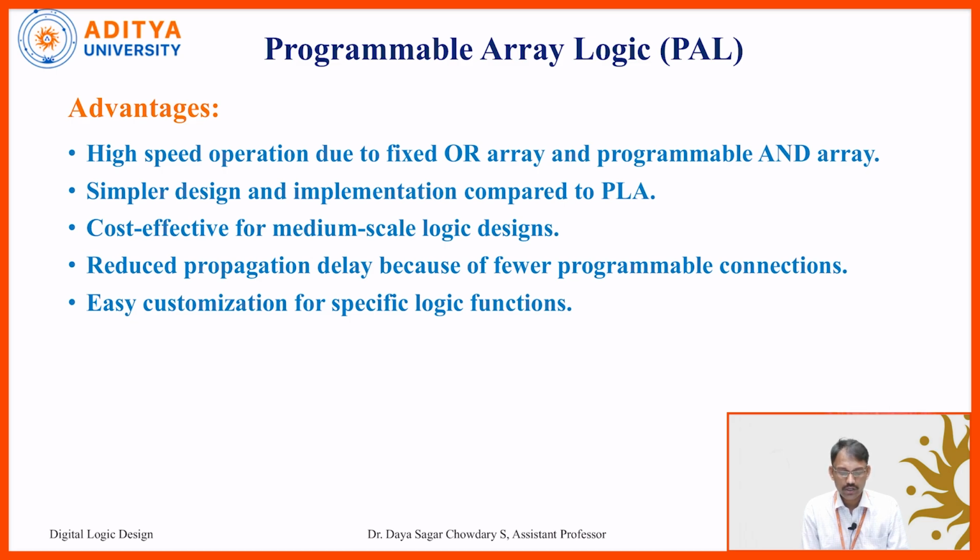And coming to the advantages of PAL: high speed operation due to fixed OR array and programmable AND array, simpler design when compared to PLA, cost effective for medium scale logic designs, and reduced propagation delay because of fewer programmable connections. Only AND gates are programmable, that is why fewer programmable connections. Easy customization for specific logic functions. Example 3 we can construct easily with the help of PAL.